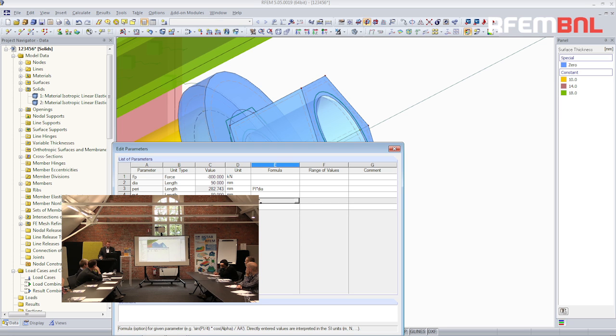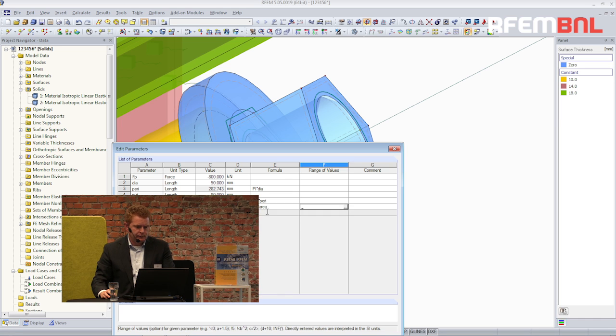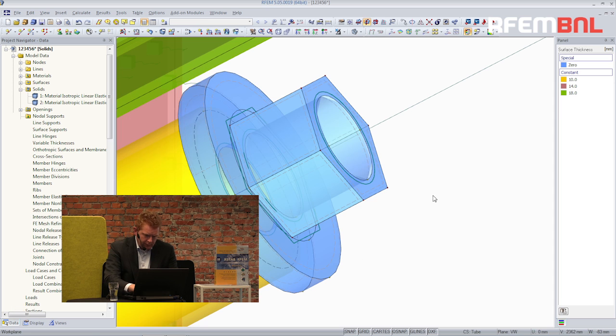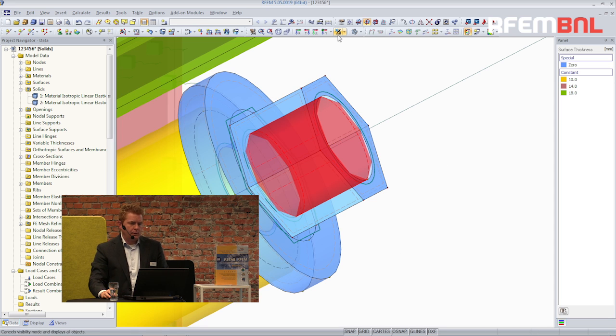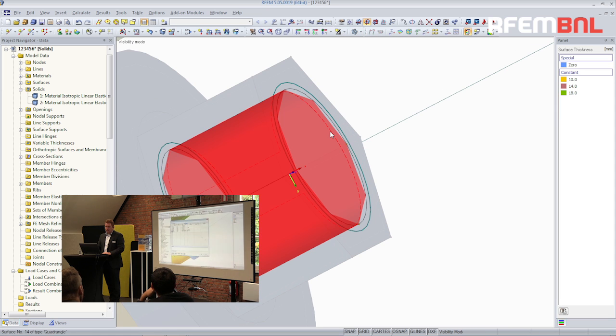So let's switch to millimeters. Like that. Okay. And then the area of the inside of the nut is nut times pi. Like that. Okay. And then you have some stress. So the pre-stress is real stress again, and it is FP divided by area. Okay. That's the value I have to add at the end.